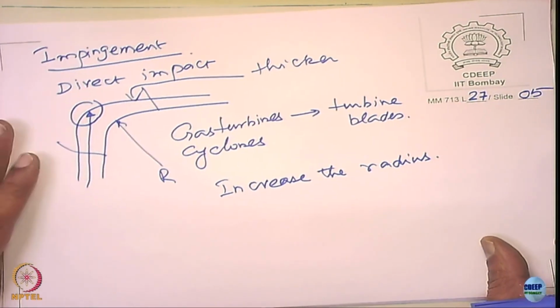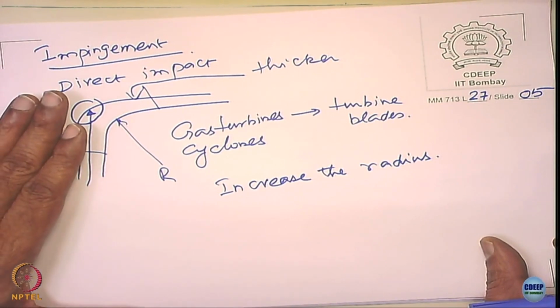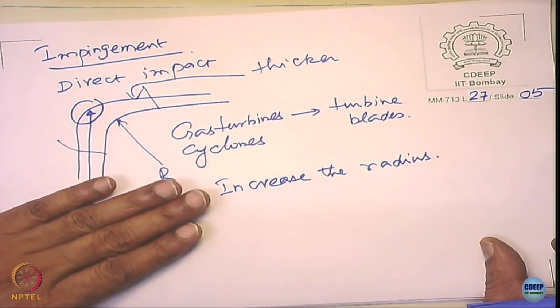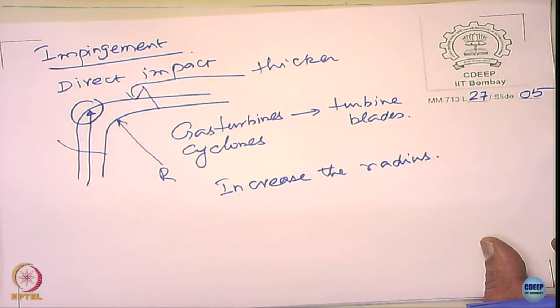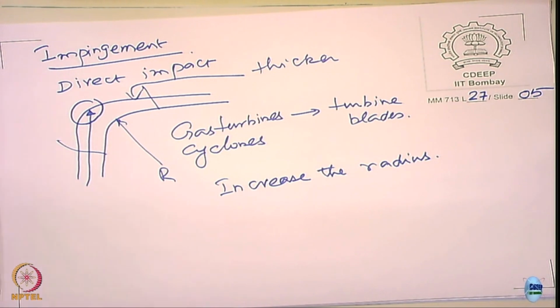So when you look at this, one thing becomes clear, that design plays a very important role in minimizing erosion corrosion, right. When I say design, all that reduces the impact, impingement, and turbulence can increase the erosion corrosion resistance of the system. So it's a design parameter as much as a material parameter, as well as the environmental conditions operating in a given system.